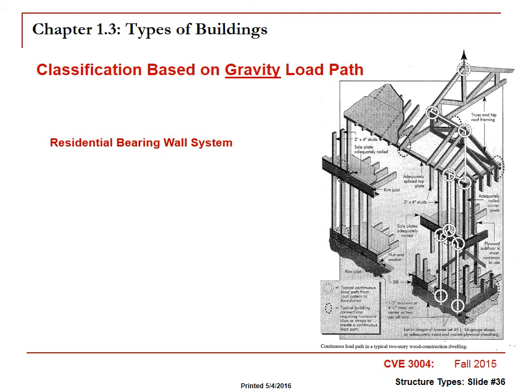But if you look at that roof truss, it has to sit where it bears, where we'd say, hey, we saw there's a little pin there when we were doing statics. There's no pin there in real life, but that truss does bear on a wall. And those loads from that wall are going to have to be transferred to the bearing wall below and ultimately to the foundation system.